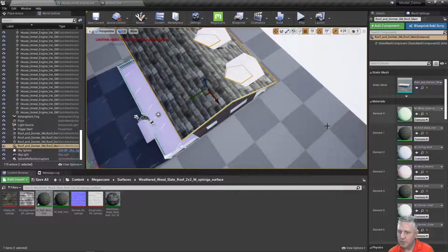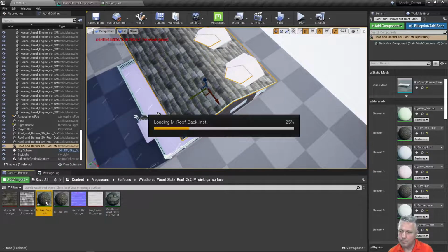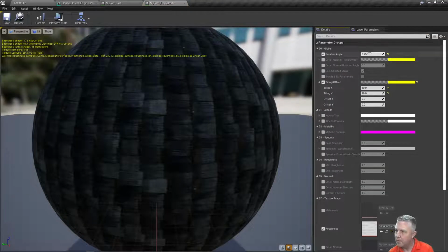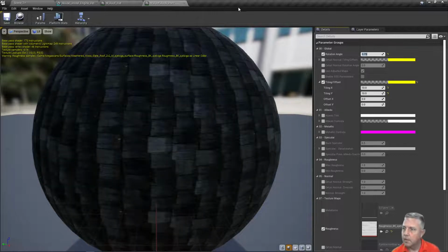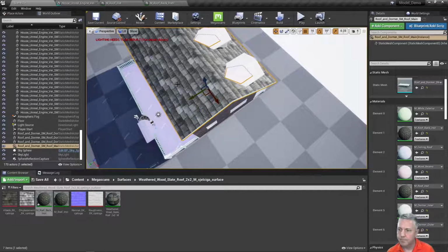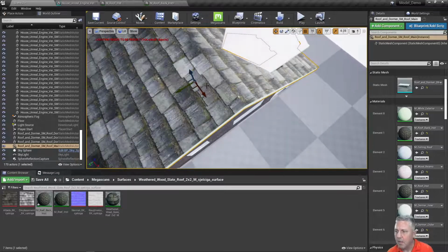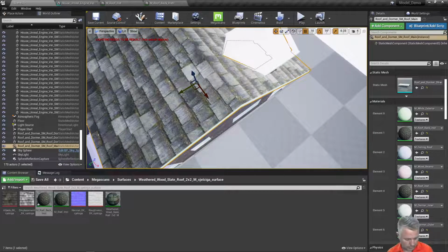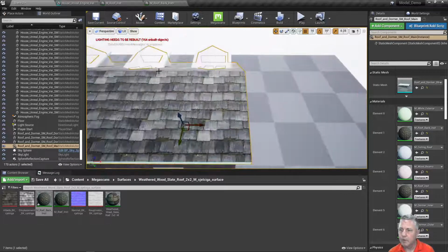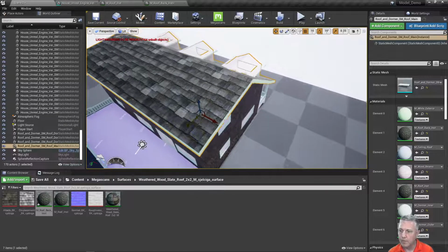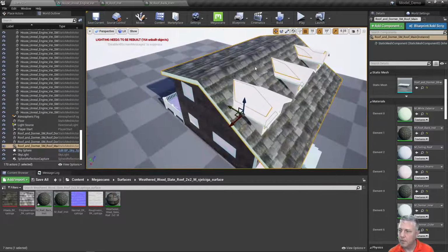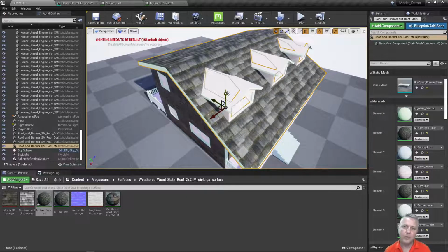And now we just got to rotate it around. So if I open this up, remember we rotated at 0.25 and we want it to go the opposite direction. So this should be 0.75. And if we take a look, it is. Then we can also line up almost exactly correct. So there we go. Now we have the roof on that part of the house. The dormer will work the same way, and it's the same with the rest of the materials.